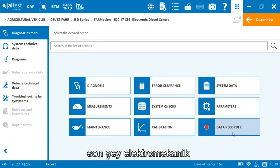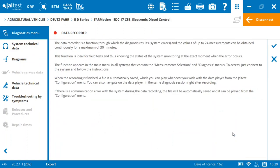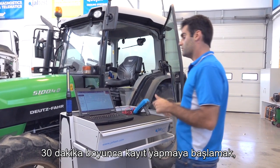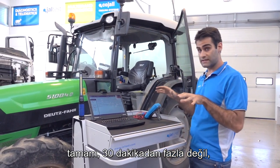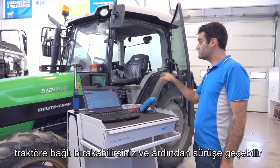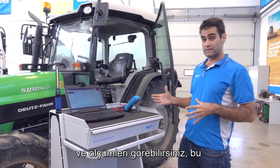The last thing is the data recorder. That's very interesting for the electromechanics. What we can do here is select a certain amount of measurements, and then we start recording for 30 minutes, okay? Not more, 30 minutes. You can leave the laptop and your Jaltest device connected to the tractor, and then you can go for a drive and see the measurements.